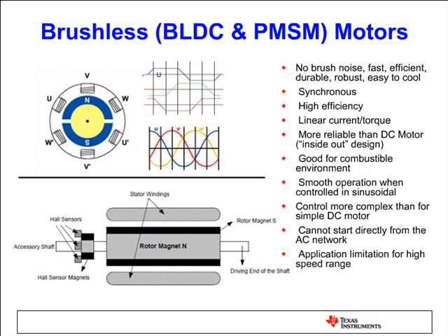As shown in this slide, the stator winding distribution is not distributed sinusoidally, but the phase coils are located as a chunk of coil turns. So that's why they are creating trapezoidal back EMF, which means that if you do not power the motor and observe the motor terminals using a scope and spin the rotor using your hand, you will see a trapezoidal waveform, which we call back EMF.